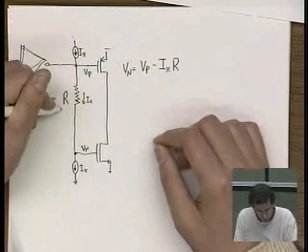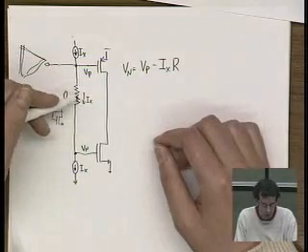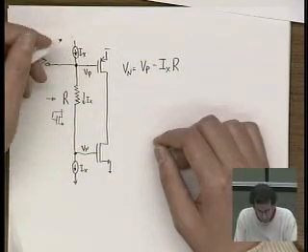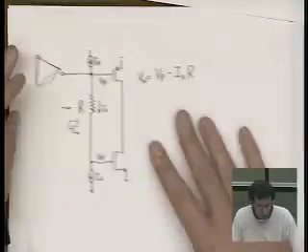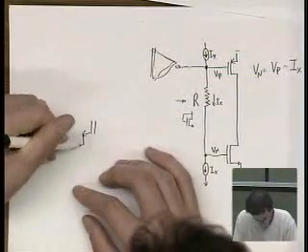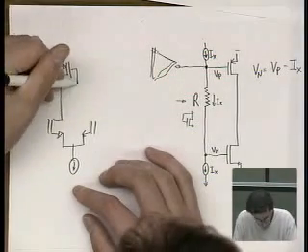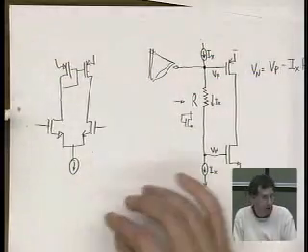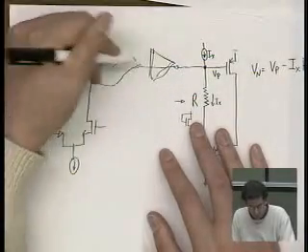Now, you could also do this with an NMOS diode or a PMOS diode. You could do it with a diode-connected transistor across this guy. Now, the issue is, let's assume that the driving amplifier, and I'll draw it over here, was an NMOS input, PMOS load diff pair, a diff to single-ended converter, and this node drove right there.